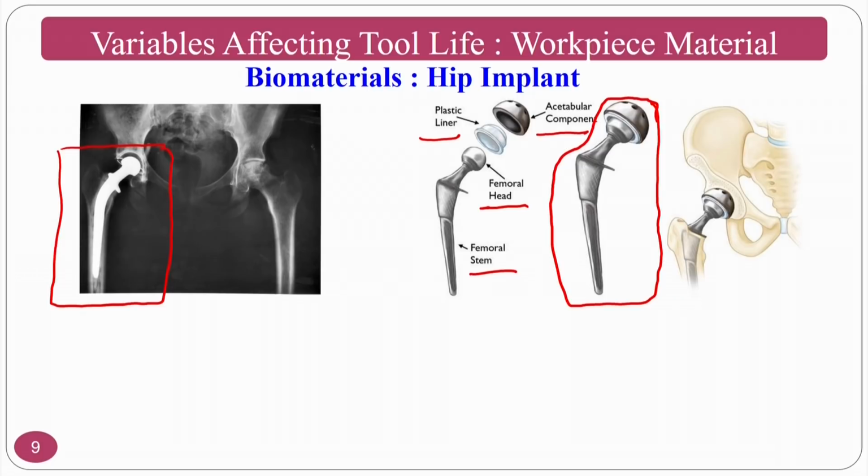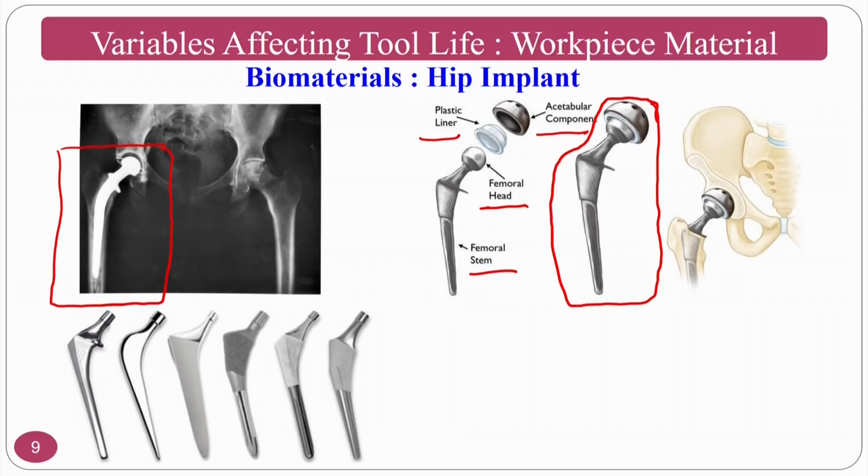Okay, so why I am emphasizing the machining of these things is this: if you have seen hard machining, if there is high temperature generation during the machining operation, the basic problem is that its metallurgical properties go bad, its surface integrity goes bad. Okay, what do you mean by surface integrity? Surface roughness plus surface metallurgy combined is called surface integrity, because whenever I do the machining operation, I want to retain the basic properties of the parent material. Okay, that is my objective.